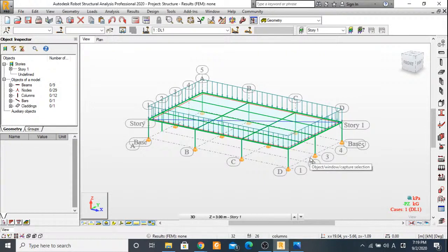That green is to show that the self weight of all of the members have been taken into consideration. All right. Unfortunately, as I explained in the beginning, the weight of the slab here includes part of the beam. All right. So we need to make sure that we add the weight of the downstand of the beam, which is the part of the beam that's not included in the slab, linearly on top of every beam.